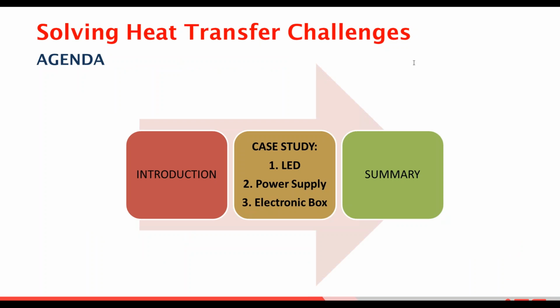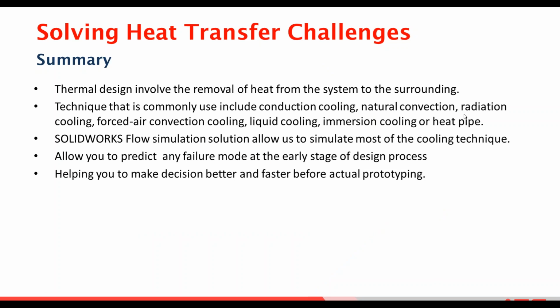So we have gone through the case studies of LED power supplies and electronic components. Let's quickly go to the summary of the whole scenario. Thermal design involves the removal of heat from a system to its surroundings. Some techniques include conduction cooling, natural convection, radiation cooling, forced air convection cooling, liquid cooling, immersion cooling, and heat pipes.